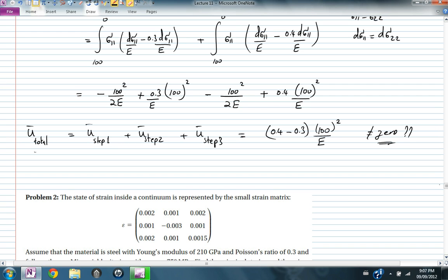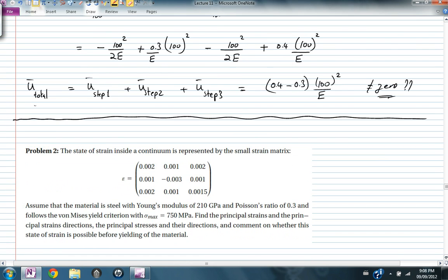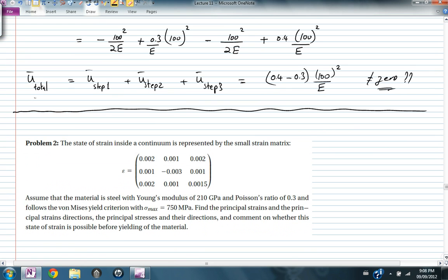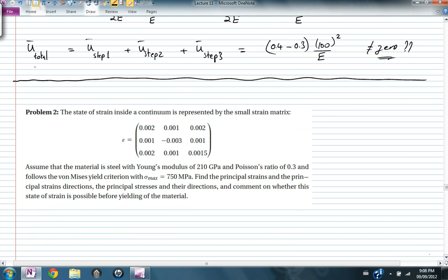But in general, a linear elastic material cannot create nor dissipate energy, and therefore the material model has to predict that the energy created or dissipated is equal to 0 when I load and unload the material. Alright, so the purpose of the first problem was to show why the relationship between the stress and the strain has to be symmetric, why the matrix of coefficients that relates the vector of stresses and the vector representation of the strains has to be symmetric.